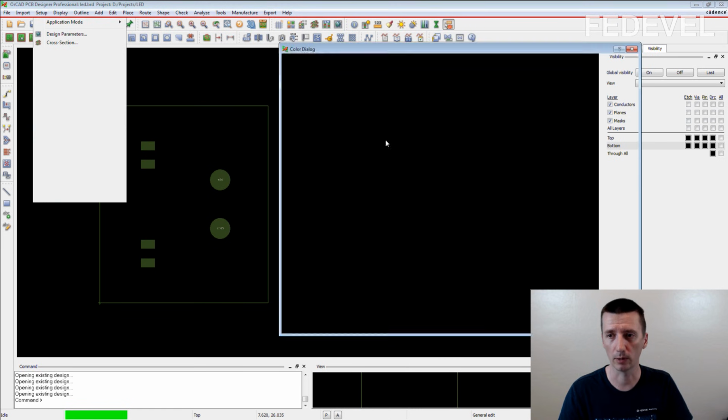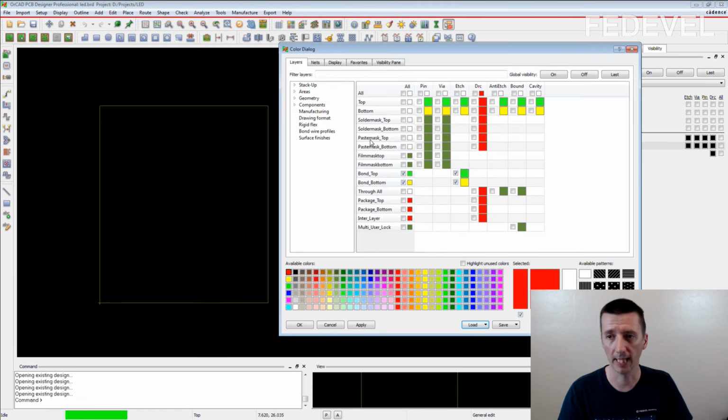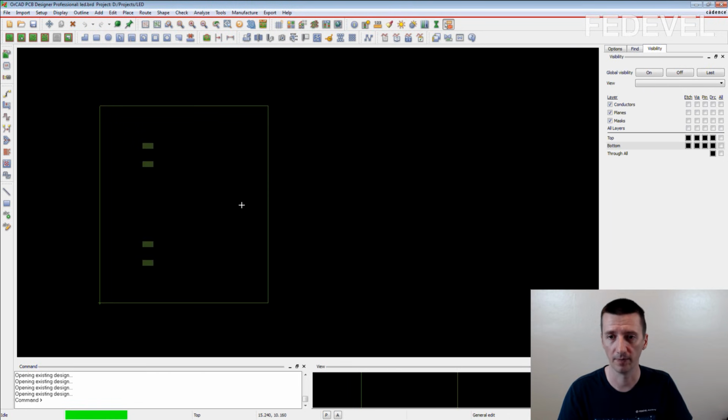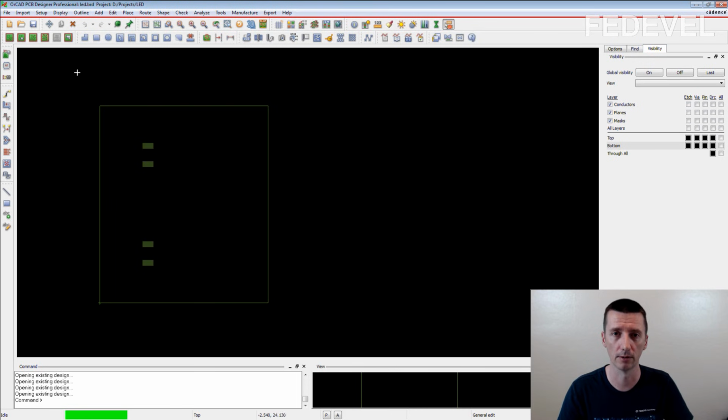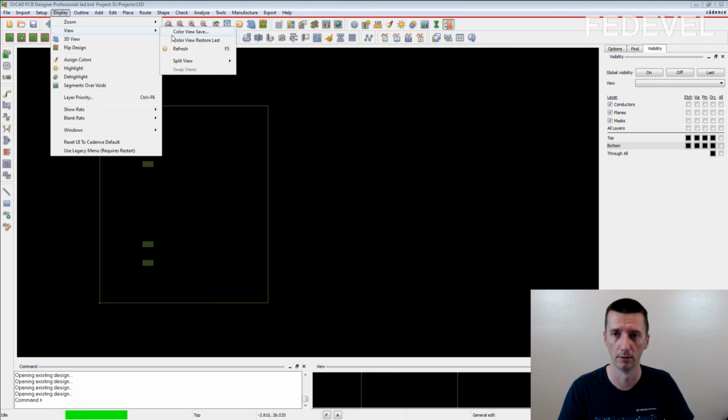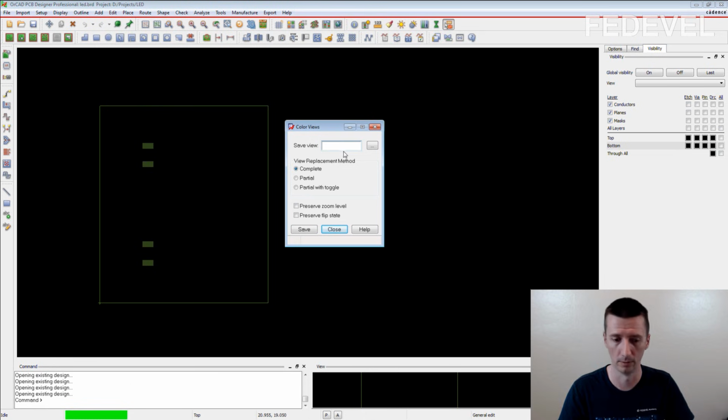And also I'm going to create paste mask view. This is the layer where the solder is applied for SMD components. So here is SMD resistor, and we need to apply the solder on the pads to solder down the components. Oops, like this.